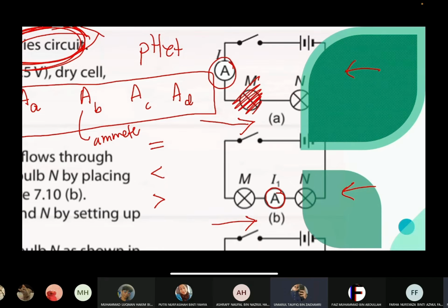Alright. So that's the conclusion for series circuit. For series circuit, current is equal everywhere. Voltage, V1 plus V2 will equal V, and resistance R equals R1 plus R2. Now you need to know the advantages and disadvantages of having circuit in series. So the main path is divided into more than one branches. Okay, so if you carry out activities, you do this.